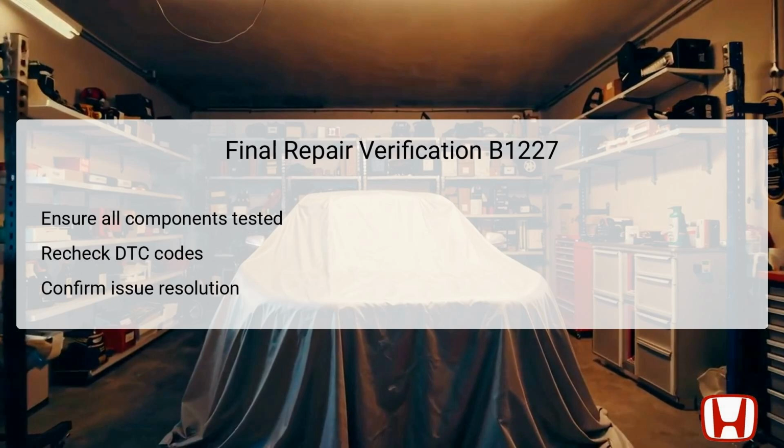Final repair verification is essential to ensure the integrity of the repair process. After all necessary repairs and parts replacement have been completed, it is crucial to conduct a final examination of all components involved. This includes rechecking all DTC codes using the HDS tool, ensuring that B1227 does not reappear. Verification also involves conducting a functional test of the climate control unit to confirm that it is now operating as intended. If any issues arise during this final phase, further inspections may be warranted.